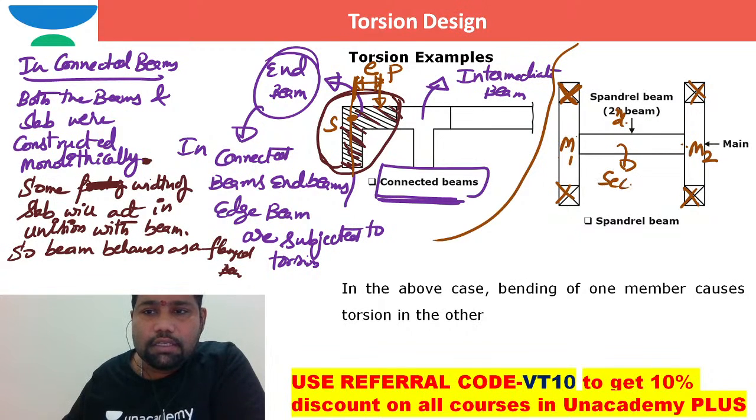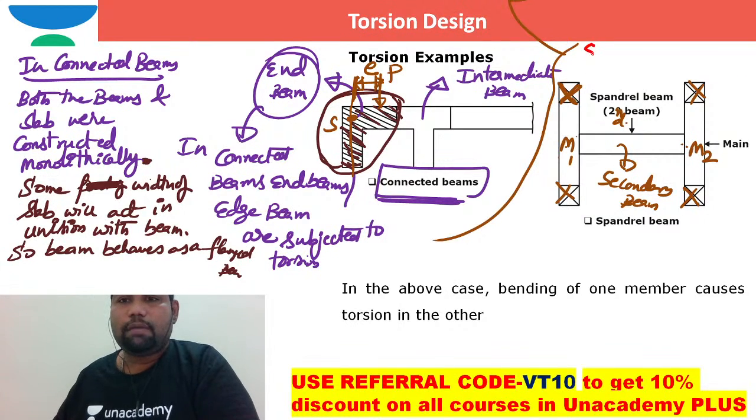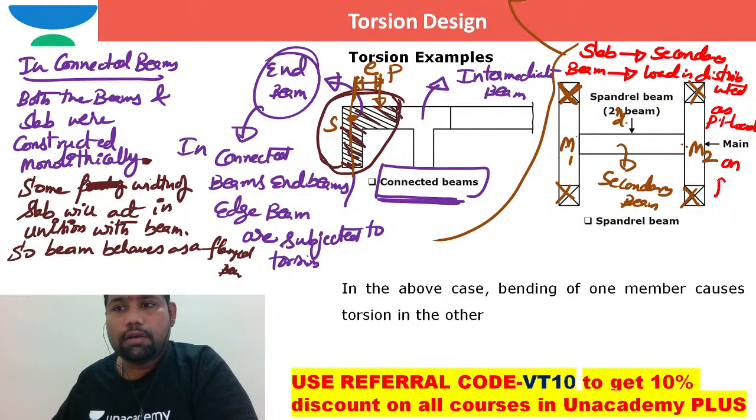This is the secondary beam. Now some people will ask us, sir, how the load distribution will happen from slab to beams and beams to columns. I just want to convey with the help of this: the slab load is taken care of by the secondary beam. From the secondary beam, the load is distributed as point load on the primary beam.